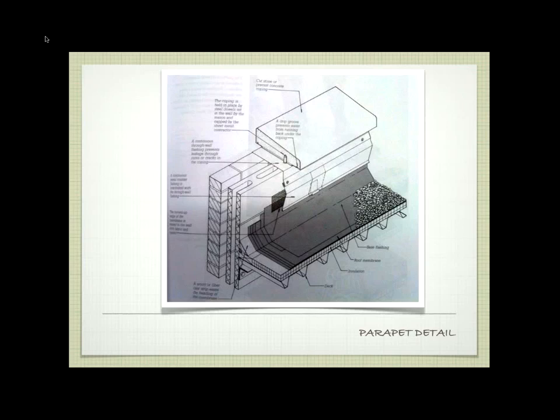If I were to take one of these asphalt sheets, I won't do it, and fold a nice tight joint in it, what would happen to it? It would crease and crack, and then I have a place where water can seep in. I want to make sure that doesn't happen, so I use this nice little 45 to wrap it up the wall nice and evenly without any cracks. So that's always the strategy. Again, I have the sheet metal flashing that extends down over that roofing to make sure that any water that falls on the top of the parapet wall will flow to the outside. Okay?